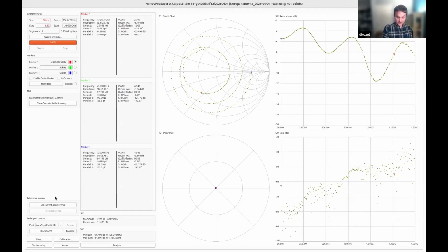One of the things to definitely know is that the NanoVNA is frankly a terrible VNA, but it's amazing for the price value. One of the big things that it fails at is stability. So this is not a device that you calibrate once, throw in your bag, and use forevermore.